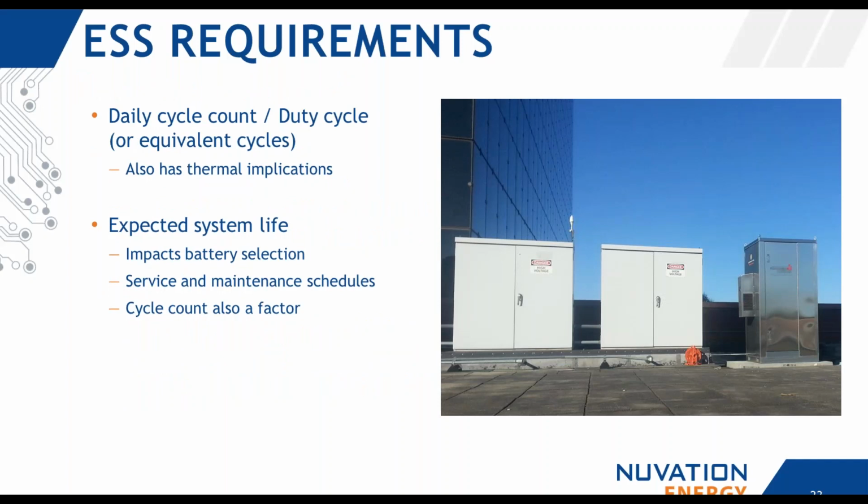The other thing to pay attention to is the cycle life of the battery. Not all battery chemistries like to be treated the same way, and they will have different life expectancies. So pay attention to that as you're choosing your energy storage system, as well as setting up your control system.